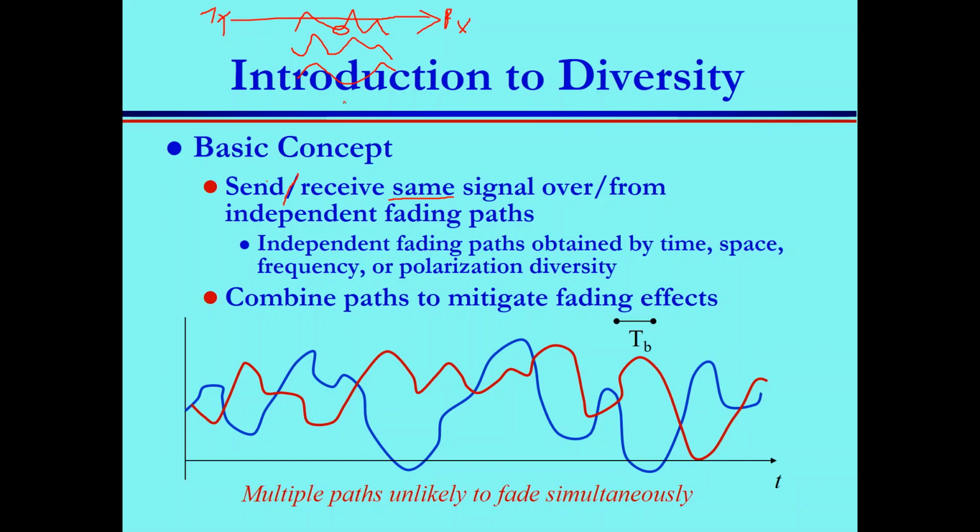Your outage decreases. Let's say now one smart student can say, okay, what if I have an infinite number of paths? When you have an infinite number of paths, you have 0 probability of making errors. And when do we have that? Joel, you know this answer from the previous course we talked about. Give me a technique that can provide a massive amount of paths so that your channel becomes hard, which means it has no fading. 5G, in 5G, massive MIMO.